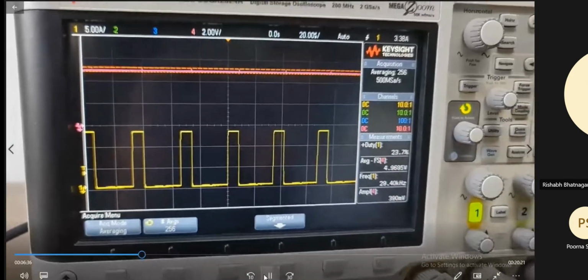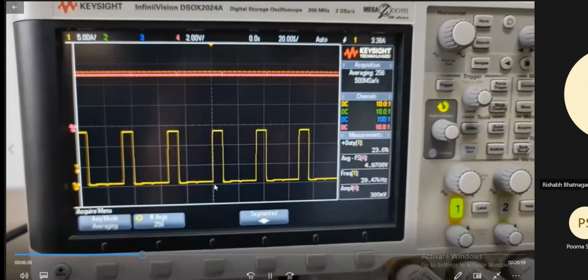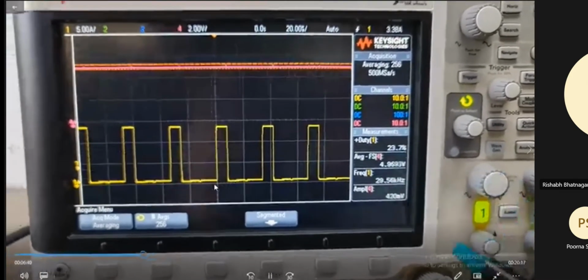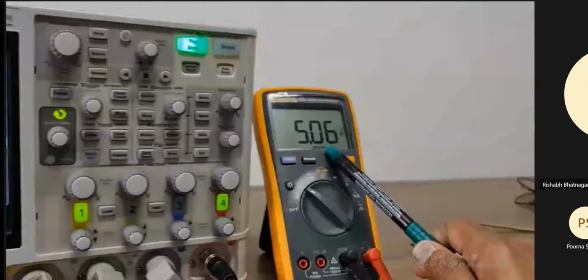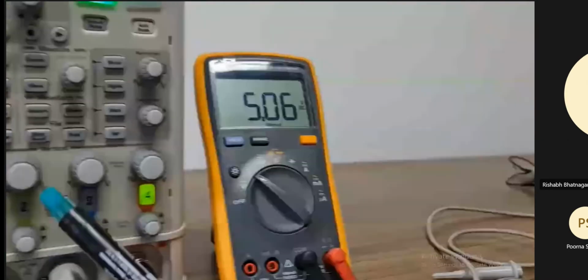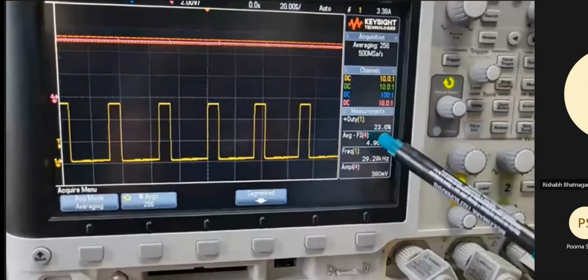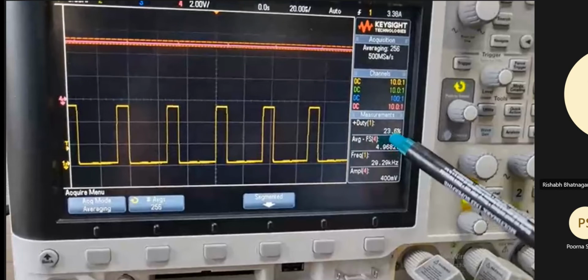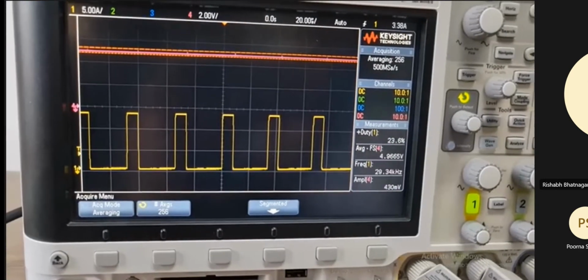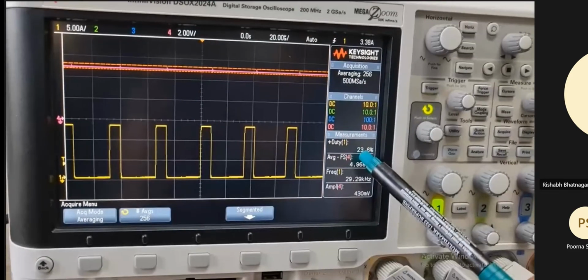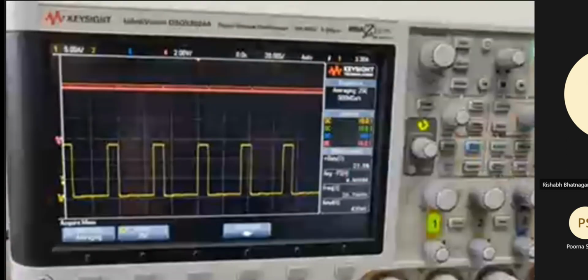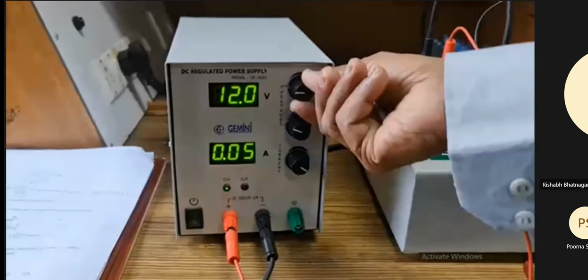At this moment, the converter is running under closed loop operation, and for an input voltage of 12 volts and a load voltage reference of 5 volts, the nominal duty ratio is close to 23.6%. If I change either the supply voltage or the load, this duty ratio will change according to the variation in input voltage or load, such that the load voltage stays close to 5 volts.